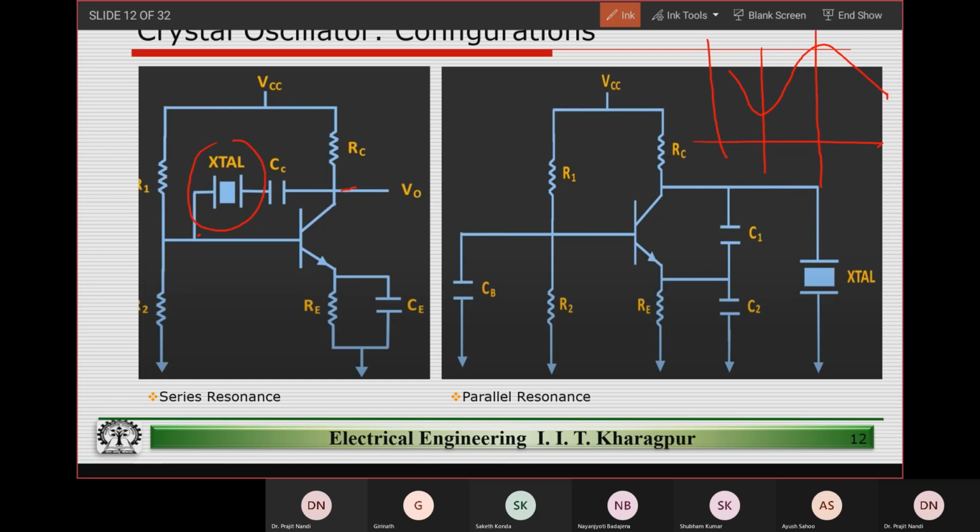See, A, the gain, is constant. In this case, the gain will depend on the resistor RE, the DC gain, and the resistance RC. So A is kind of constant. So what are we left with then? Beta. So beta in this case is going to increase, meaning when is the feedback factor more? When beta is more, right?